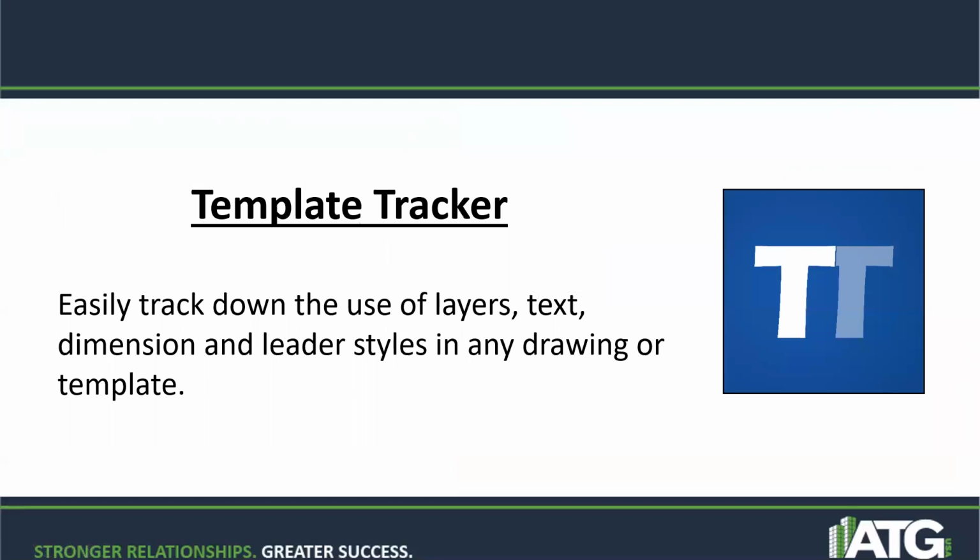Next up, we're going to talk about the template tracker tool. And again, I'll show us the project suite version and the expanded functionality in the manager suite. But the focus of this tool is to make sure that we know what our Civil 3D styles are doing. We can't delete layers, even if they're empty, even if they're not layer 0 or def points and so forth. We can't delete a layer if there's a Civil 3D style associated with it.